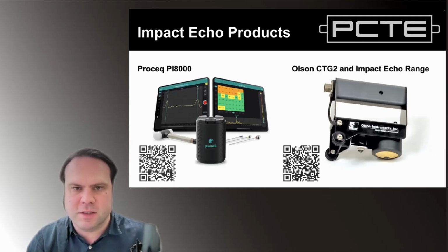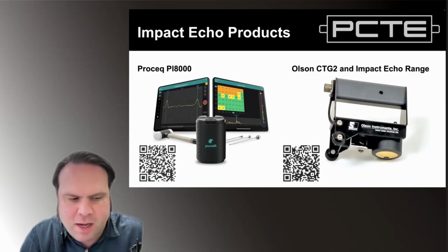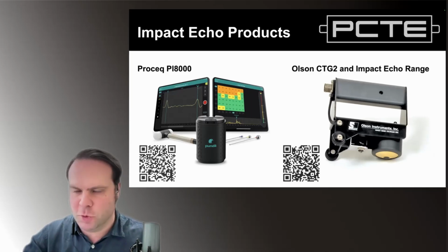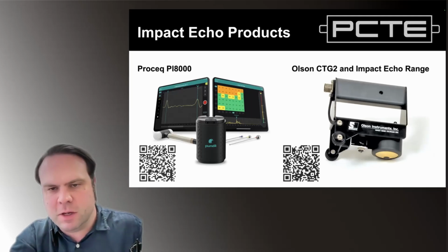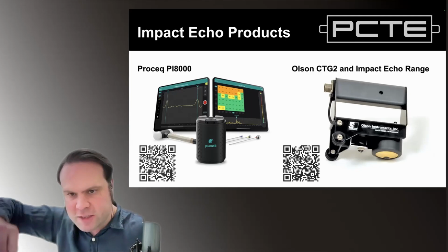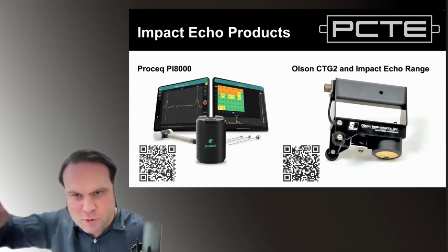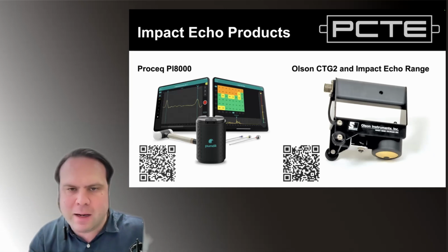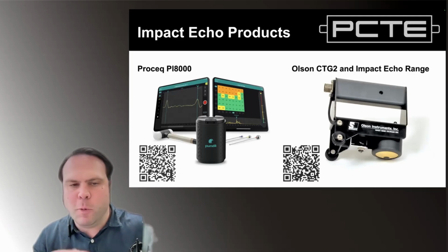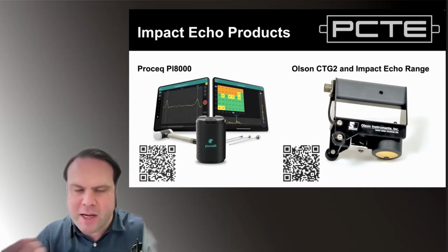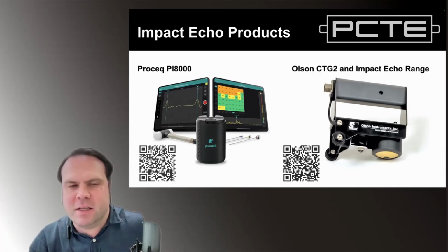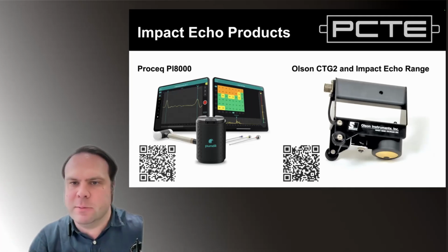I don't think you're going to lose the signal entirely, unless the entire thing becomes essentially so patchy that the signal doesn't travel. Then your test would fail. Something which is always worth being aware of: we're expecting a certain kind of resonating response, something which we can measure the dominant frequency of. If your panel deteriorated below the point where we could take that kind of response, we wouldn't be able to do a quantitative change in frequency measurement. We'd just be able to see after 100 cycles, say, the entire thing's powder, and I can't test it anymore.